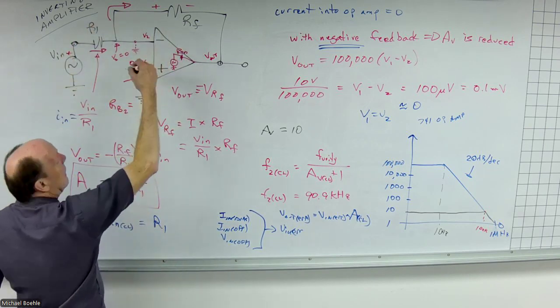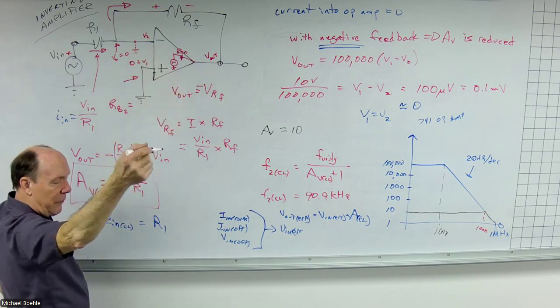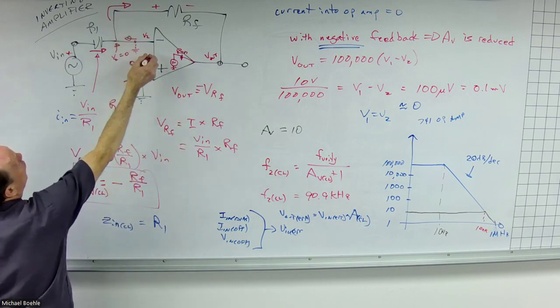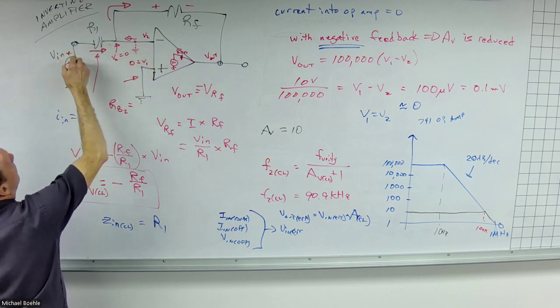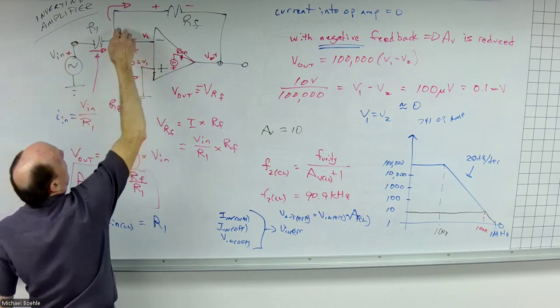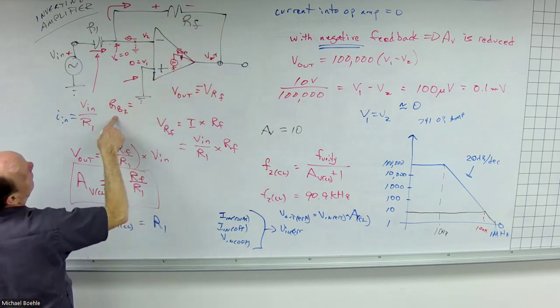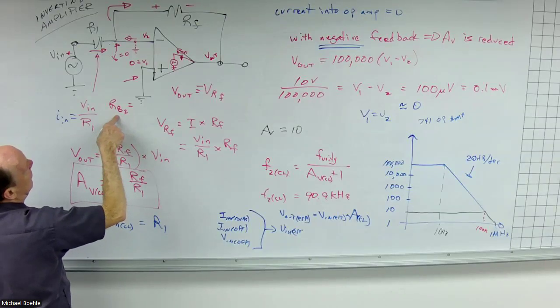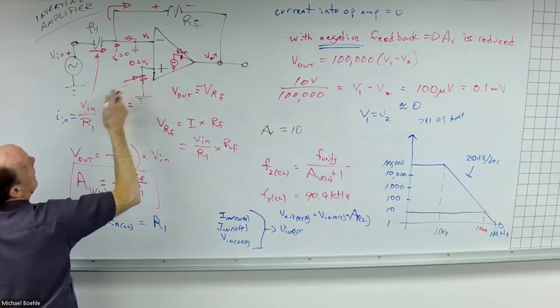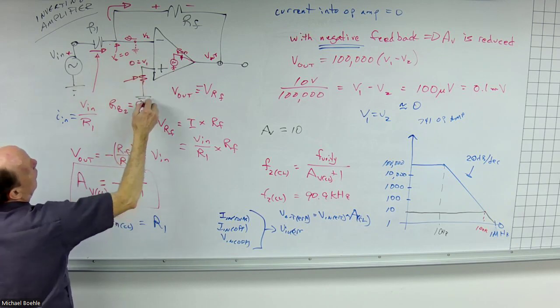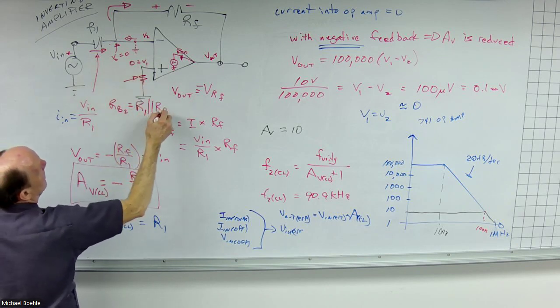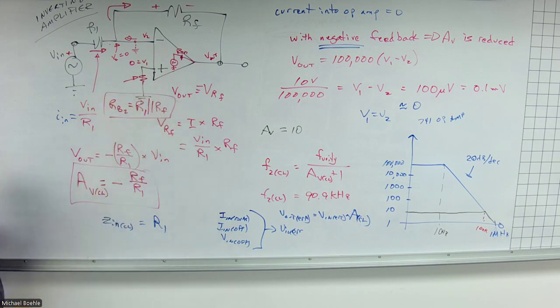And so if I do a Thevenin and look back this way, this replaces with a short, so I have R1 to ground. I have the feedback resistance through here to ground. And so we approximate an equivalent base resistance. If I want to put a resistor in here to match base resistances, it would be the parallel combination of those 2 resistors. We want to match. Inverting amp.